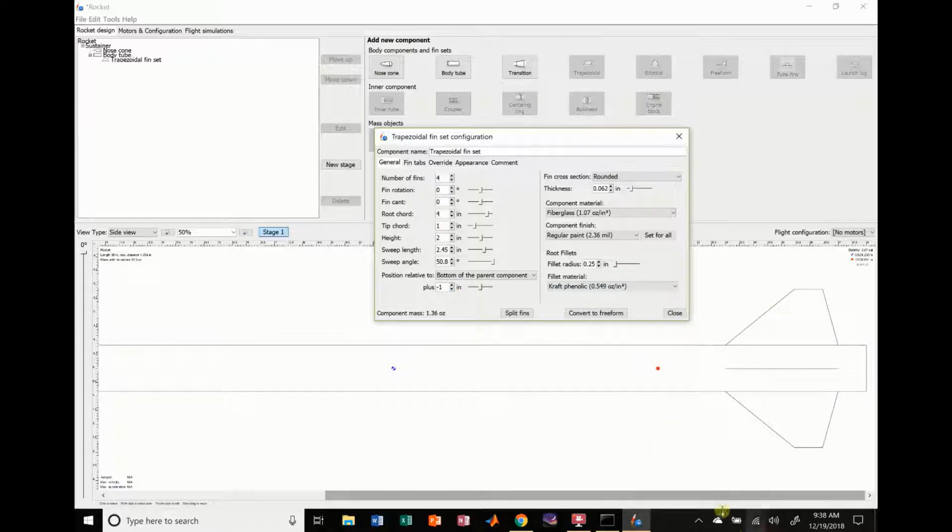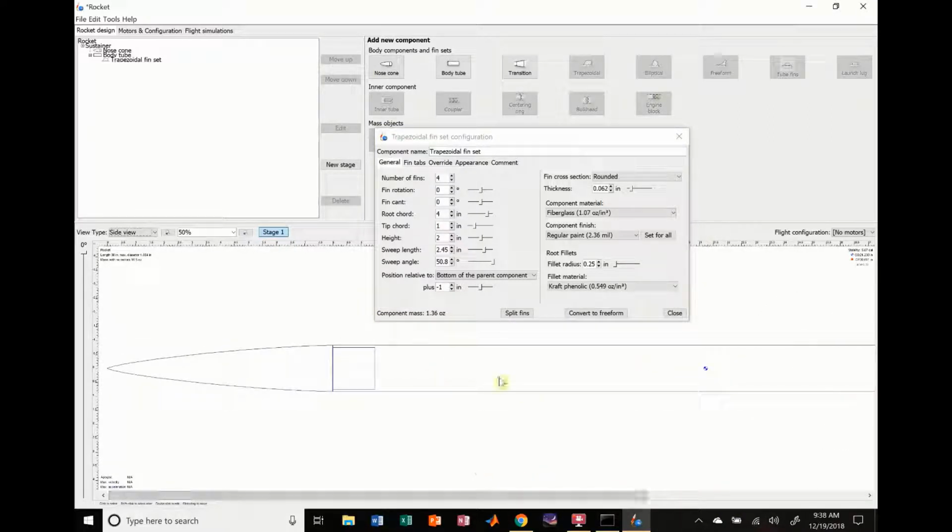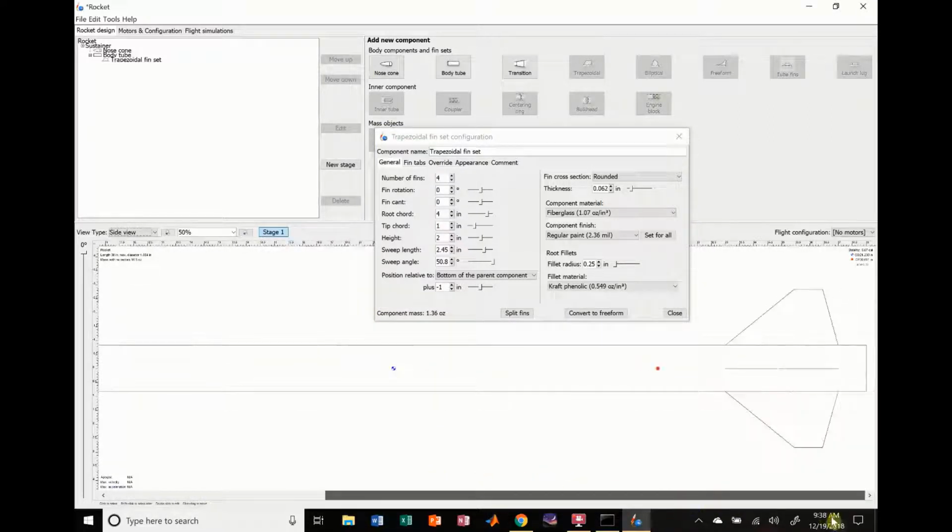when your rocket's going to be hurtling down to the ground with the parachute attached, the parachute's attached up here, and this is going to be the heaviest component of your rocket, so that should impact the ground first. And if you keep your fins like this, it's going to hit fin first, which is usually pretty weak. So it might actually snap off one of your fins. So what we typically do is we try to shift the fins up on the body up to 1 inch, but usually for smaller rockets we choose about 1/2 inch. That's pretty typical.